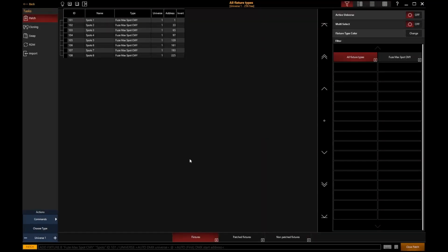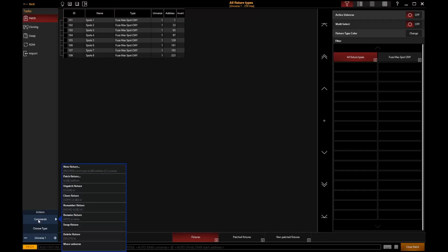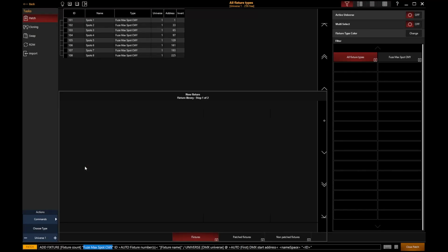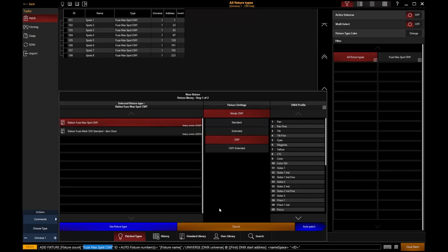In this video, we're going to take a look at patching using the command line. To do that, I'm in the patch screen already. I'm then going to go to Commands, and I'm going to say New Fixture. And this is going to give us access to the fixture library.